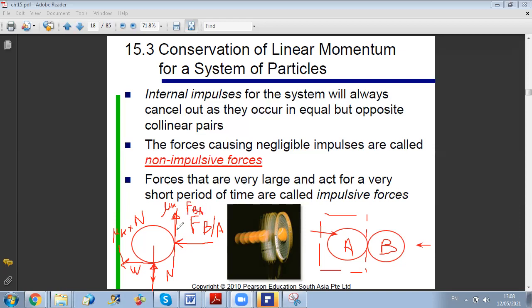Now, in this figure, if we draw the plane of contact between the two, I have the two balls, and the tangent between them. The friction mu k times F of B on A acts along the tangent. Since F of B on A is impulsive, meaning very high, mu k is usually in the range between 0.1 and 0.5, so not very small. I am multiplying a high force by a number that is not very small, so this force is comparable, perhaps one order of magnitude less than F of B on A, but I cannot neglect it.